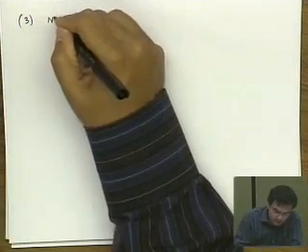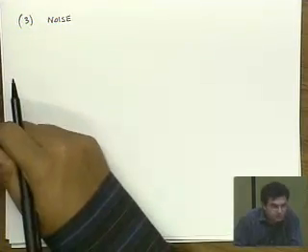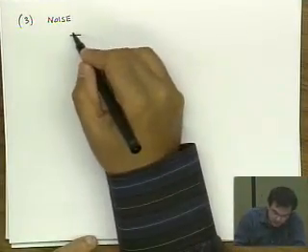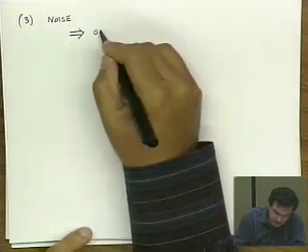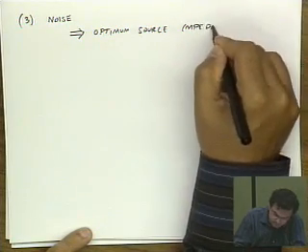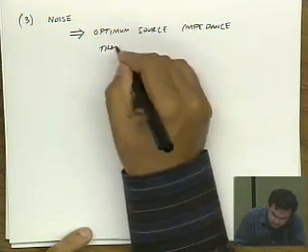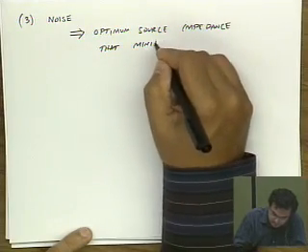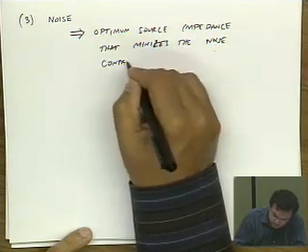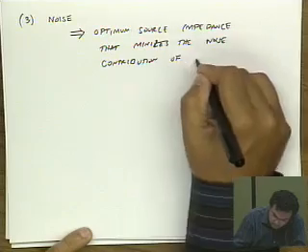Well, we haven't talked about it yet, but in this class we're going to spend a lot of time talking about noise. When you design amplifiers, generally you want to design one that introduces as little noise into our system as possible. I won't go through the details, but let's just say there is an optimum source impedance that minimizes the noise contribution of a two-port.